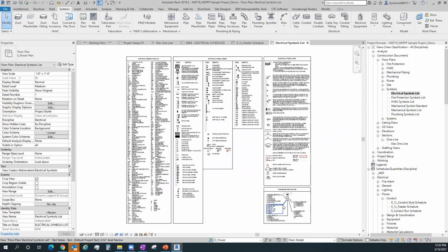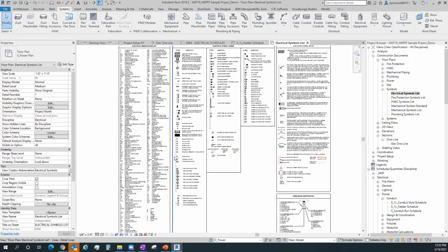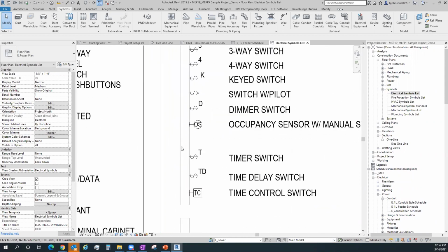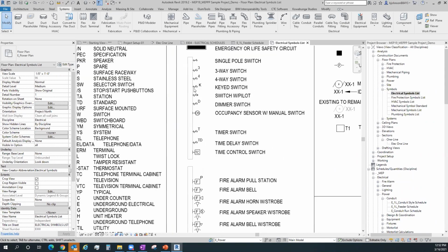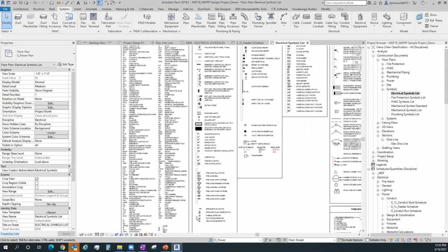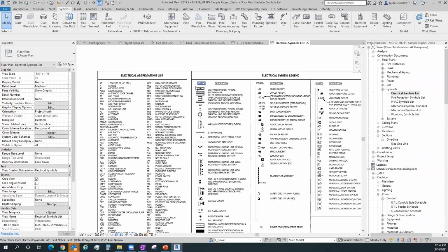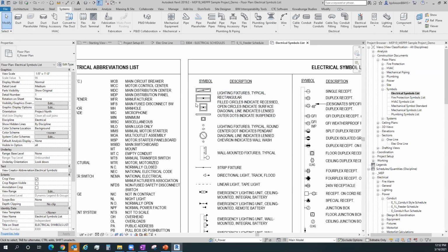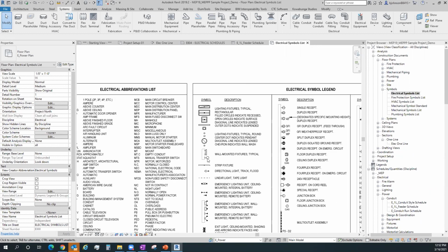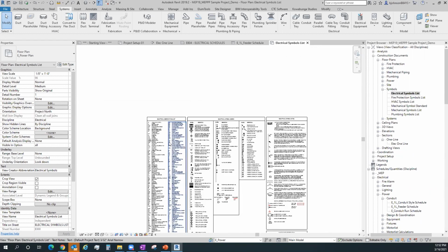in my drawing that's also being controlled by a design option, and this one is a dynamic legend. So in my dynamic legend, I actually do have a segment of wall in this alternate universe of my design option, right? I have a wall with all of my wall-based objects placed on it for my symbols library. I have another view that's a ceiling view where I've placed a ceiling and I've put all my ceiling-based objects in there.